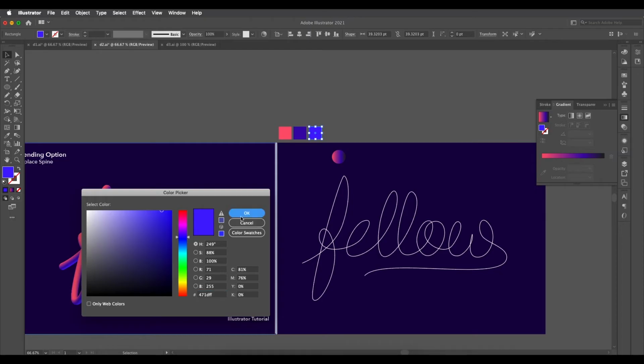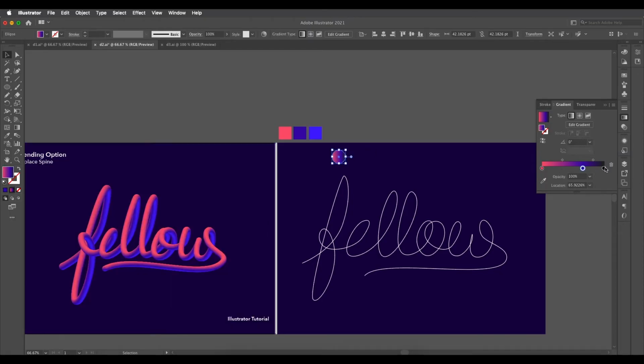On Control C, okay, and then select the shape and select the third slider, choose RGB, right, and just paste it over there, and here we go, we have given that nice color. Now we need to change the angle. I'll just keep it to 90 degree, or maybe just reverse it, minus 90, keep it here, and the second one I'll just place it here. So I just create a duplicate of it, and we'll keep the same gradient color to this.